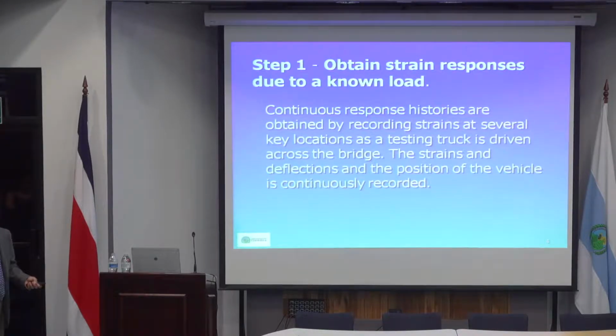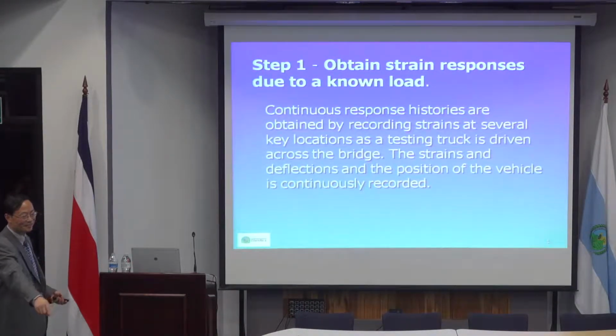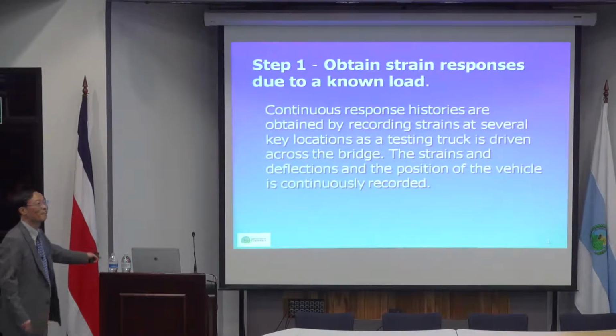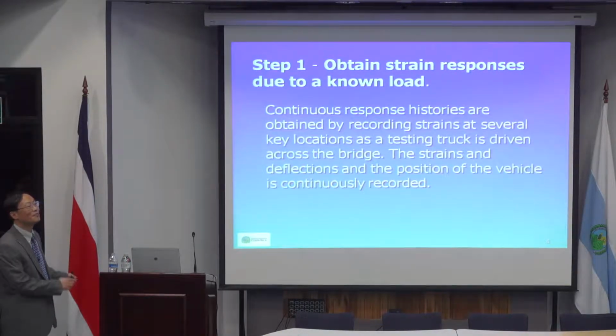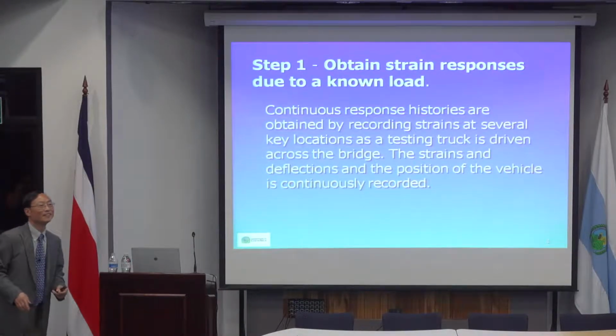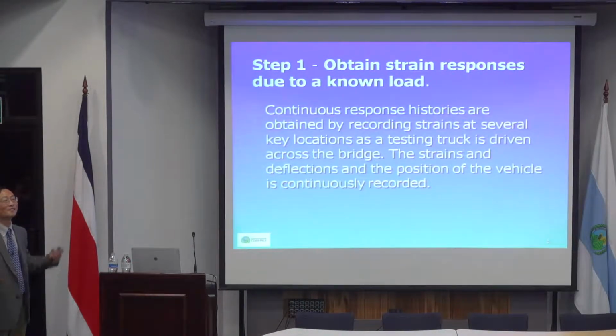But once you do the load test, you find that, because the arch is so long, even if you put the truck close to here, it actually only takes 55%, and the other will take 45% instead of 25%. So you don't need to design for a much larger live load than necessary, because it's so complex. It's not like a simply supported beam where you put a load here and know how much reaction each has. It's a three-dimensional thing.